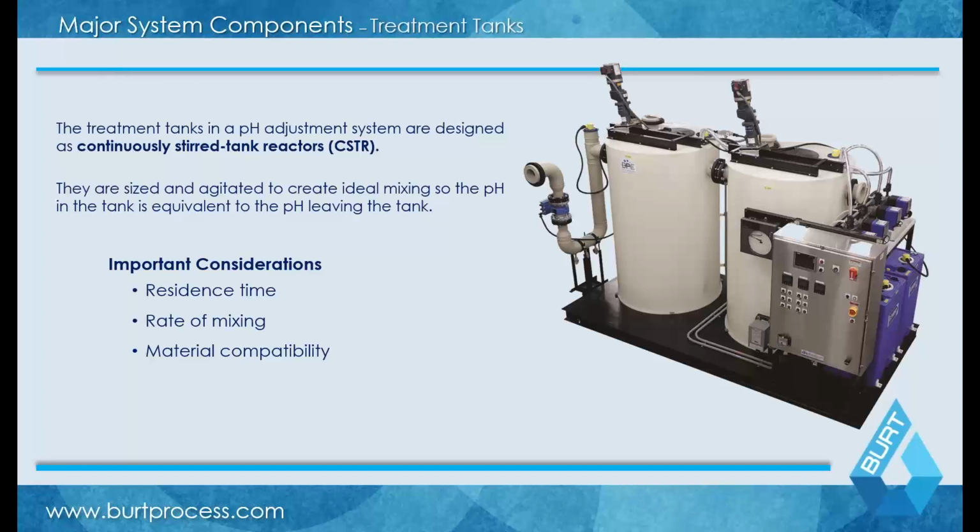And really, when people ask me what's most critical in a pH system, whether it's having a consistent waste profile or consistent flow rate, it's by far and away the more important factor, more than the actual nature of the waste. You can adjust the chemicals a lot. You can do a lot of turn down in them. Having a fairly consistent flow rate into your system is actually very beneficial. And the residency time is really there to help catch those fluctuations in the overall flow rate.